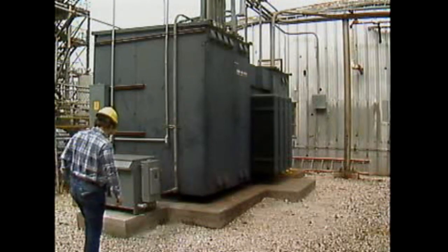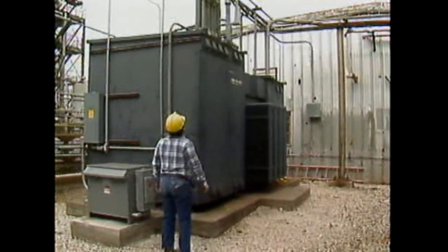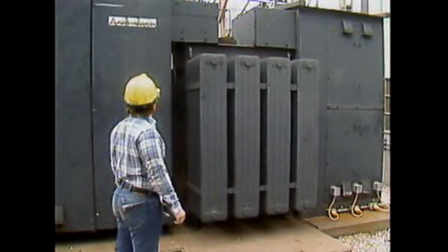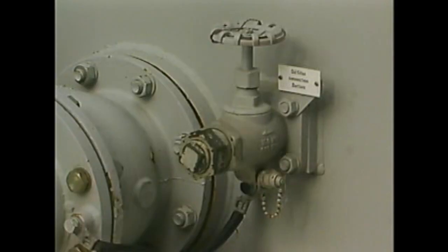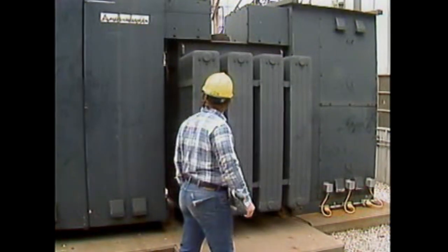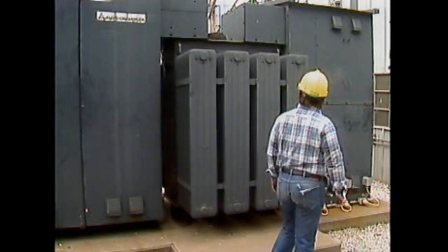During the inspection, if any loose or broken wires are noticed, they should be reported right away. Also, the affected area should be kept clear until the problem has been corrected. The casing of an oil-cooled transformer should be checked for leaks and signs of corrosion that can result in leaks. A good place to check is the joints where piping is connected to the casing. When inspecting the transformer's radiators, remove any paper or debris that might be blocking the radiators and interfering with cooling.